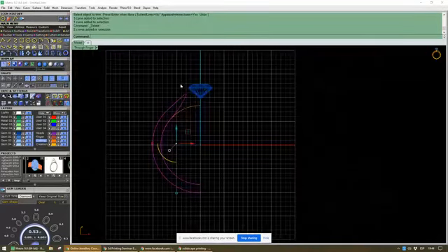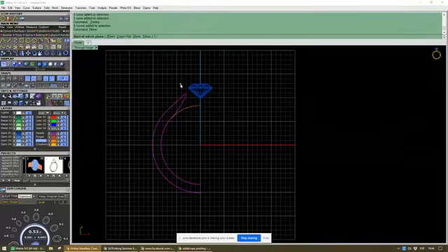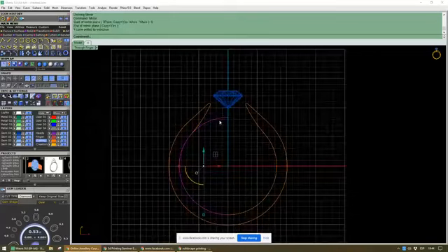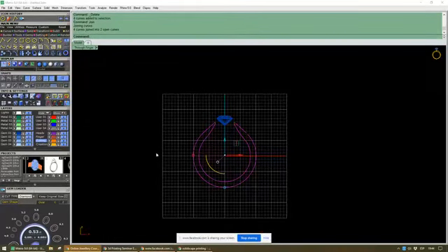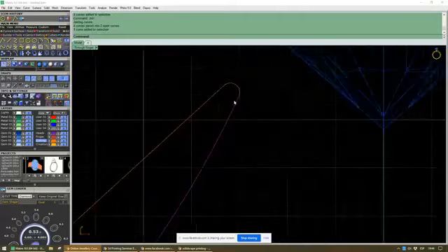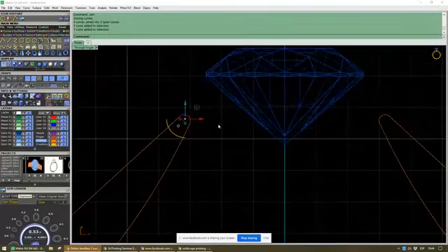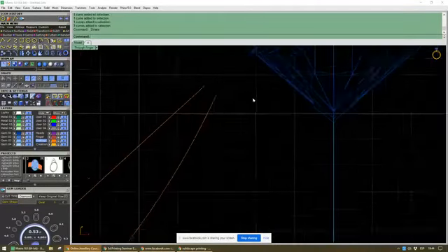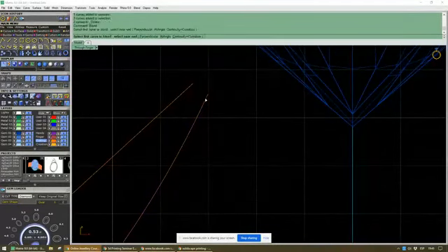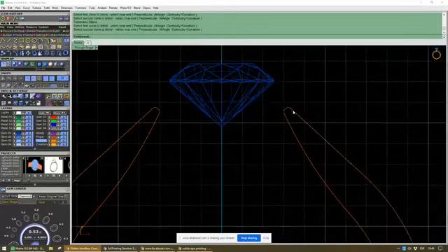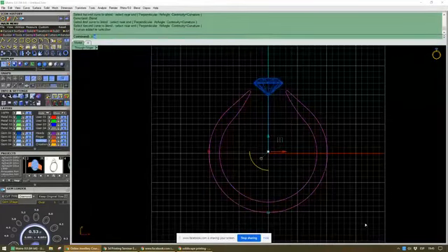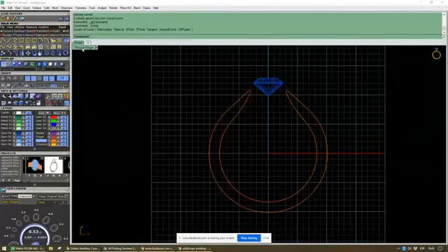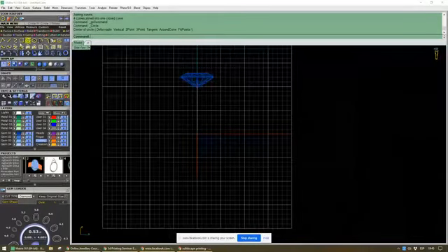Okay, so that's the outside. I'm just gonna make the mirror of it. Well, mirror, I get rid of this. So now I join it. Two open curves. See, that's a little problem I have here because I made a bit of a mistake. I can just do this and use blend curve. So I blend this with this and this with this. Okay, so now it's gonna be one closed curve. So now I'm gonna draw the side profile.